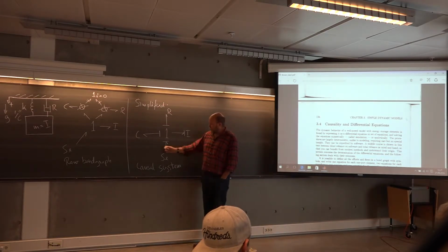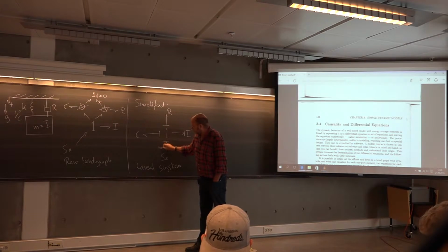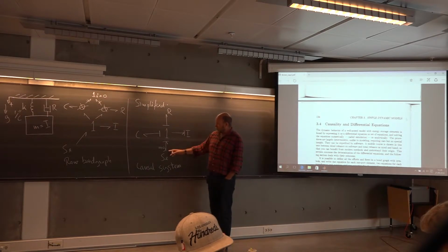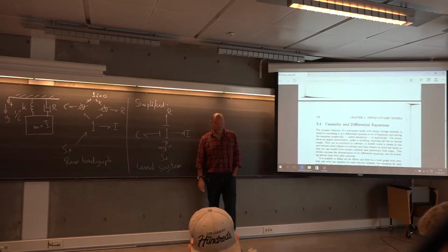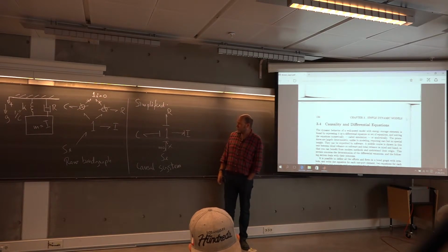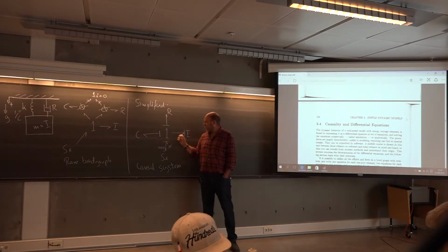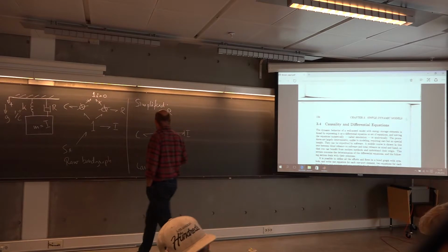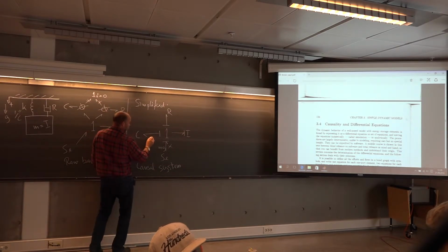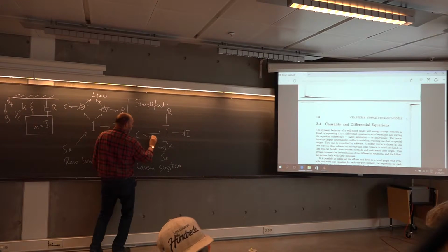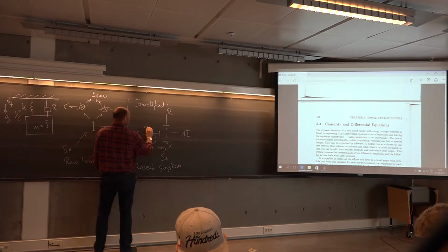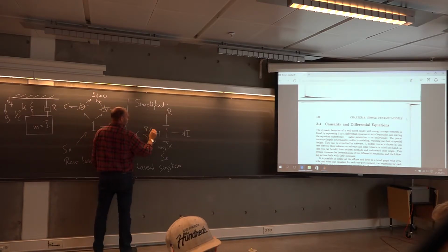We have a force from the source. So here I can write an effort mg. That's the gravity force. On the other side, from a source, we are not interested in the flow there, so just write an x. For the C and the I element on the integral form, when you have them on the correct form, you can immediately do the following. Here you now have a q dot with a circle around, and on the other side as an effort, only q,